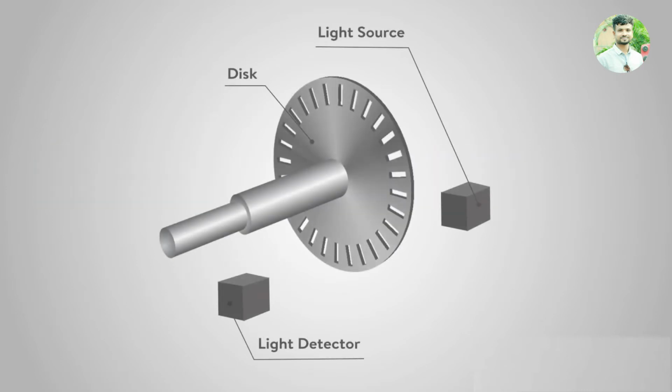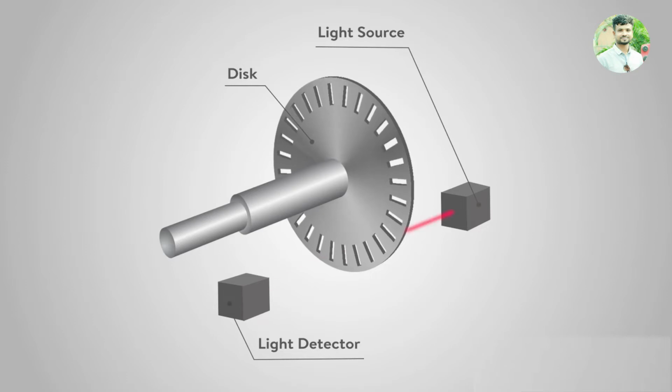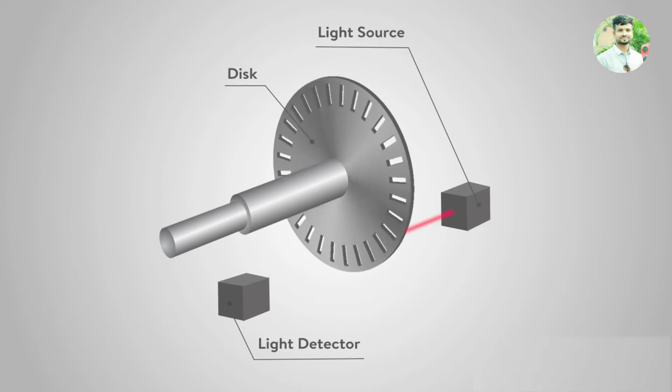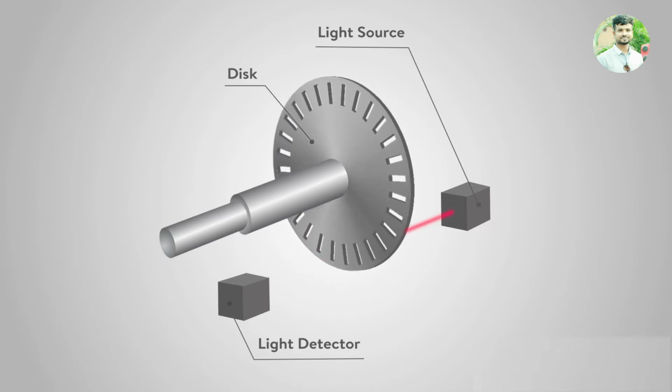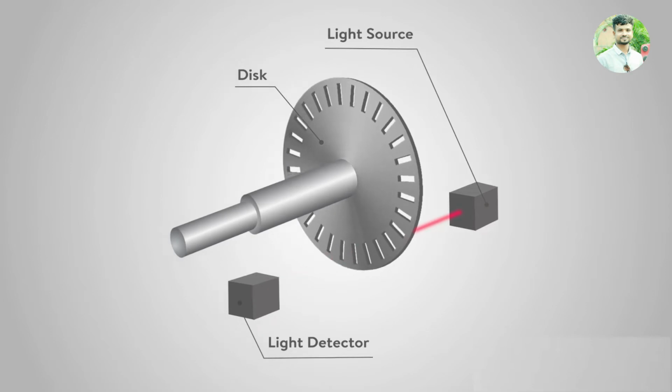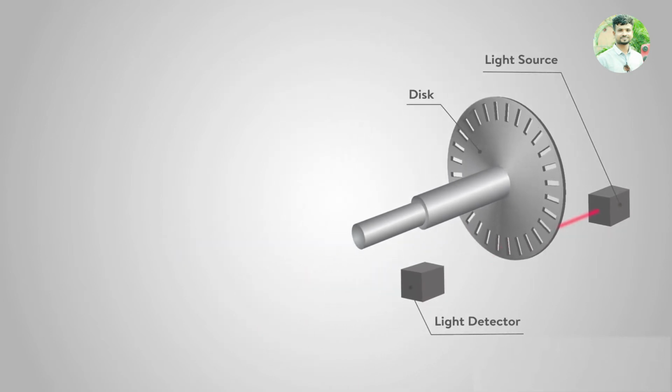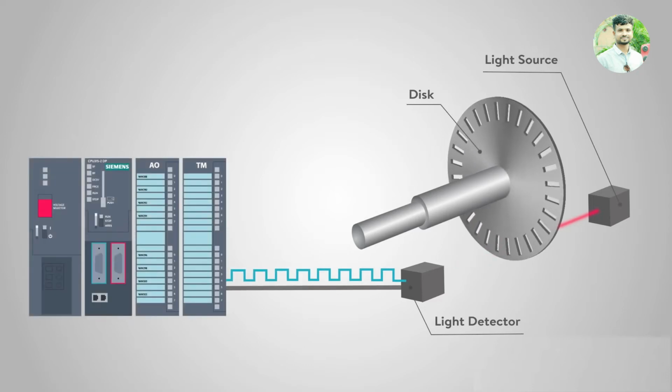But for now, an example of an incremental optical type encoder uses a beam of light that passes through a disc that has opaque lines in a specific pattern, somewhat like the spokes of a wheel. On the other side of the disc is a photosensing device that will interpret the light based on the pattern of the disc. Picture a shutter blocking and unblocking the light. The pulses of light are then converted to an electrical signal to be sent back to the processor.